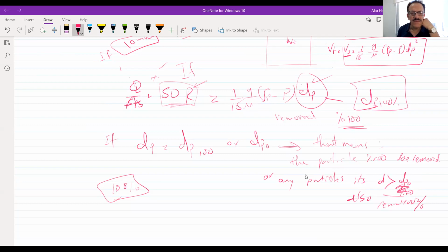Now, you have the Q, the accounted flow that you have to send to the plant. Now, what's left for you? I have this and I have that. So we just need to know the cross-sectional area, which is equal to pi d squared over 4. When the diameter is the only unknown, you can find the required diameter for that tank to be capable of removing this particle size. This is the way that we use for design of such tanks.